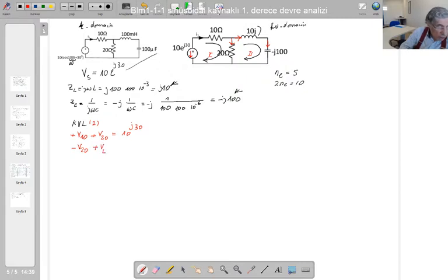So these are all phasors. So we are in the frequency domain, and we are writing the frequency domain Kirchhoff voltage law equations in phasor form. So VL directions are the same. For the VC directions are the same, plus VC, the capacitor voltage phasor, equal to 0. So when you have written all these equations, you could do some checks.